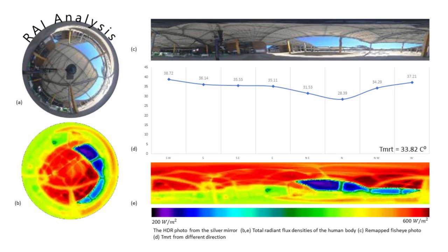The result shows the radiation flux from each direction. A significant portion comes from the canopy itself as a line of radiation. It is possible to divide the directions into a series of numbers and assess them individually or as a total MRT. As shown in this diagram, the lowest radiation comes from the area including the sky, which highlights the role of the sky as a cool surface.